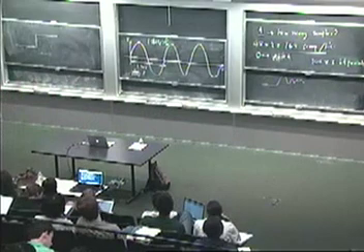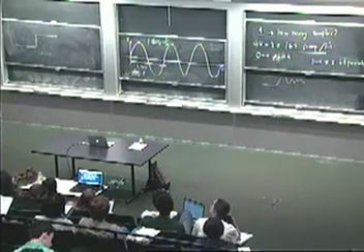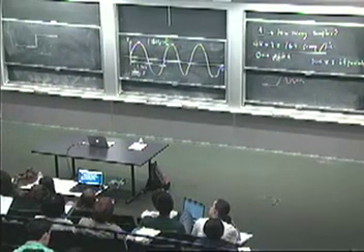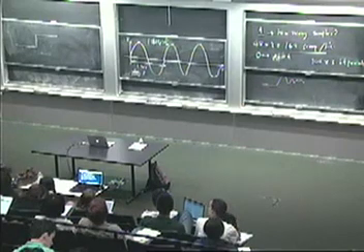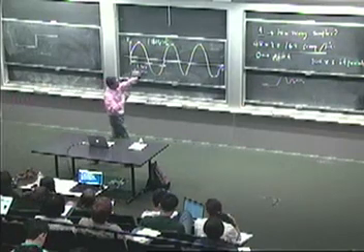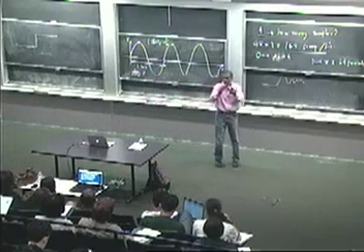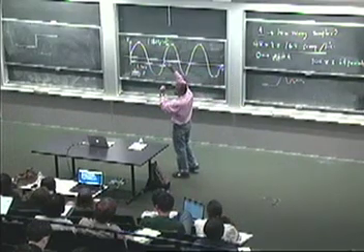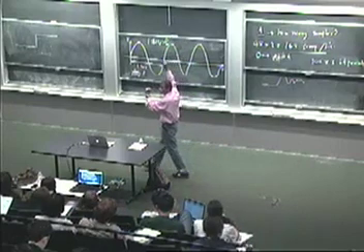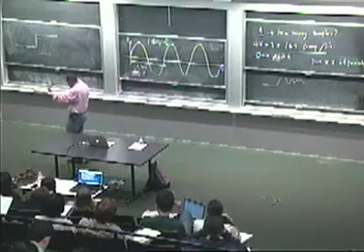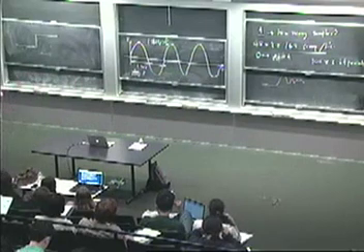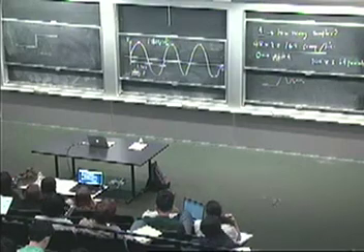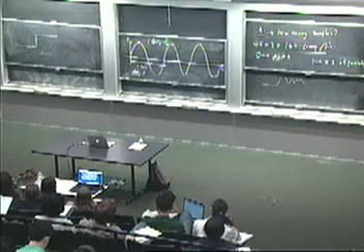So for any given 3-bit sequence at the input, there's a 3-bit sample sequence at the output that corresponds to a number of samples equal to the samples per bit multiplied by 3. And each of those generates one of those trajectories through this picture. If you generate that picture and you find that there's a very clean gap between all possible combinations of these bit sequences, as in this case here, then it means that you've been able to decode.